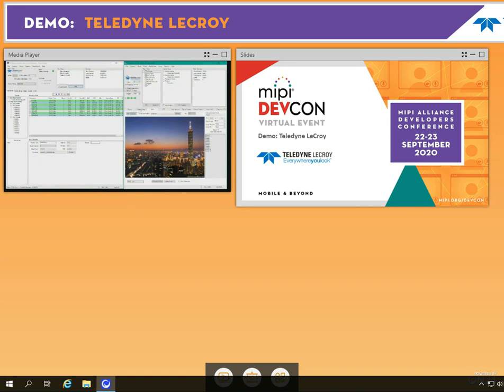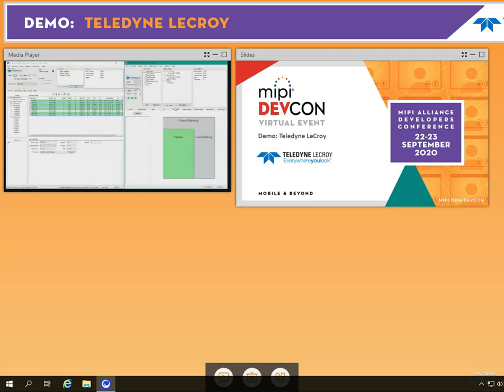The user can also choose to compare the captured frame with a golden image. By selecting Compare Frames and getting the video data, the captured image will be compared with the golden image, and the number of pixel errors will be displayed beside the frame number. If the View Differences button is selected, those pixels in error from the golden image will also be displayed as a black pixel. Once you've played back the captured image, you can do a video analysis.